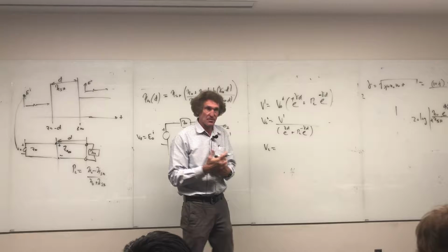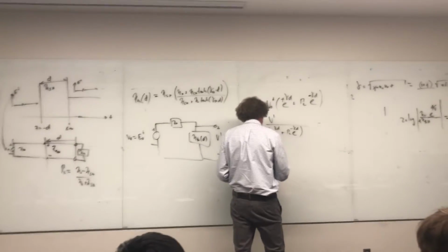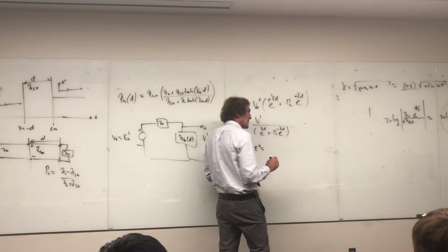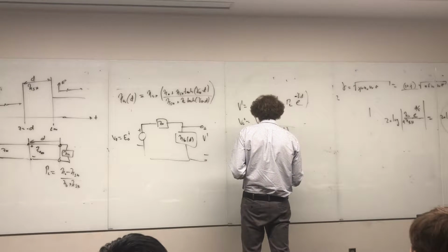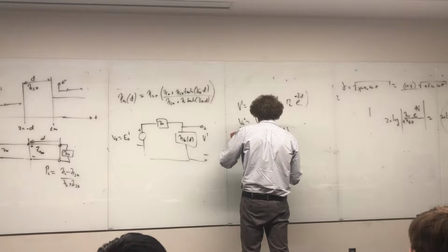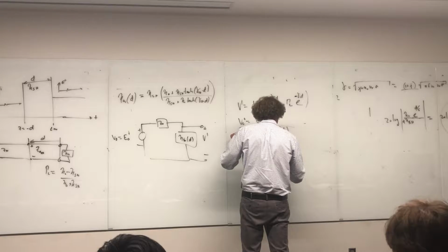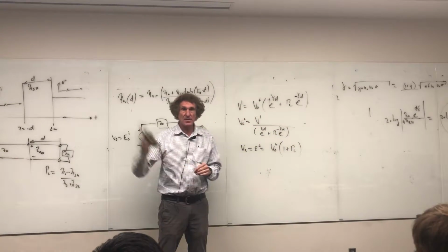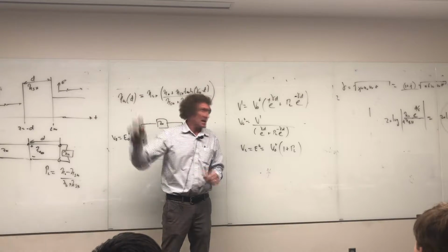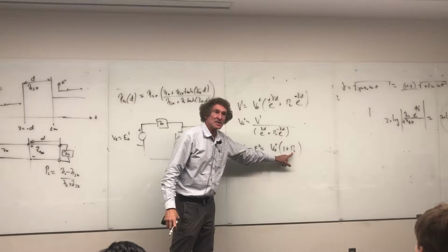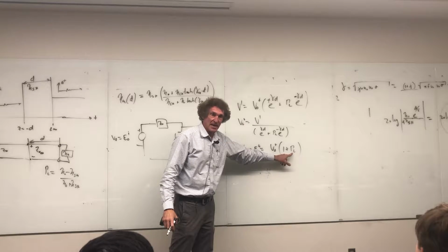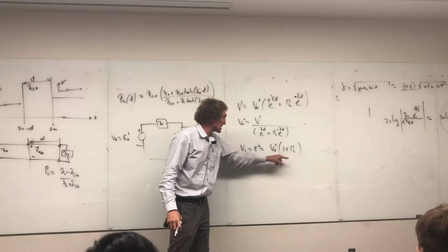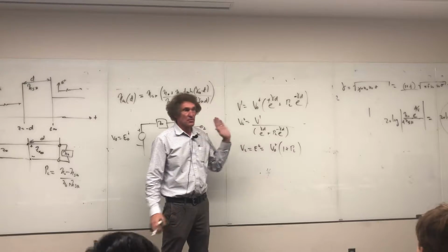This is how much of the electric field would be transmitted. It's the same thing as the transmitted field. And in fact, that would be equal to just this V0 times 1 plus the reflection coefficient of the load. Do you all remember that one? Remember that? Now the thing is that gamma L is complex, and you don't take a magnitude of it. It's 1 plus gamma L times V0 that will be the transmitted field.